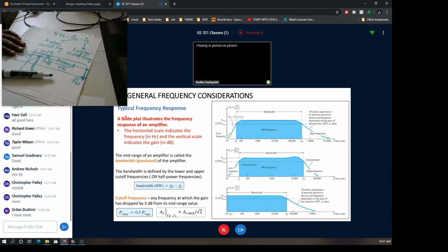In most cases all amplifiers in the market have this frequency response already sketched to you, with the frequency axis in log scale, and the gain provided by the amplifier in absolute value magnitude in dB scale.